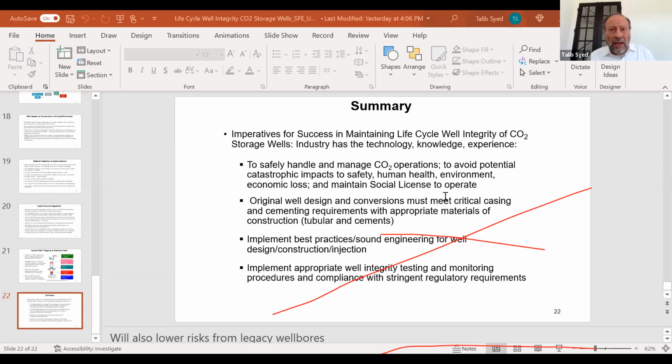Yeah, for CO2 EOR, you want to make sure that your mobility ratio is 1 and above, positive. But again, the screening that has to be done is very critical in order to make sure that your EOR project is a success with CO2. And remember also, we've got water alternating gas. So in many CO2 floods, just putting CO2 by itself is not that successful. You have to use a WAG process where you alternate a slug of water and then a slug of CO2. And that was presented by Parag earlier this morning, what Oxy is doing in their operations.